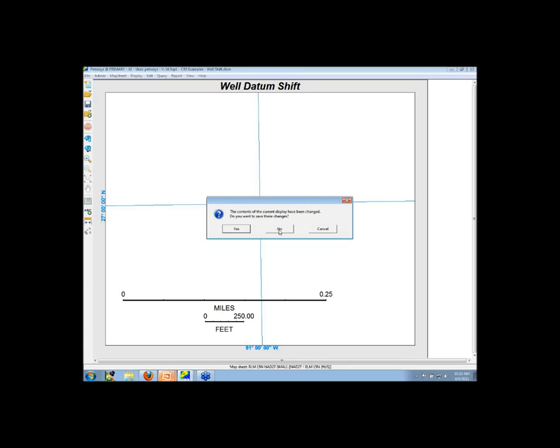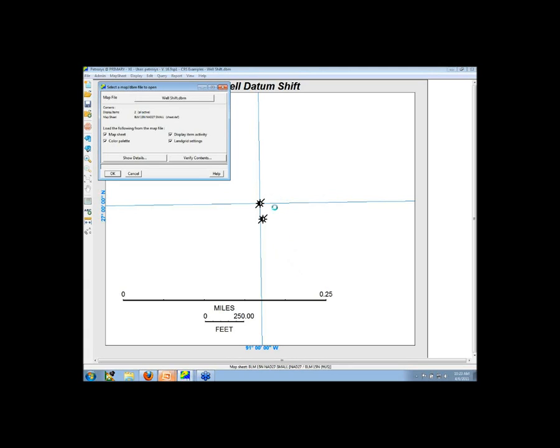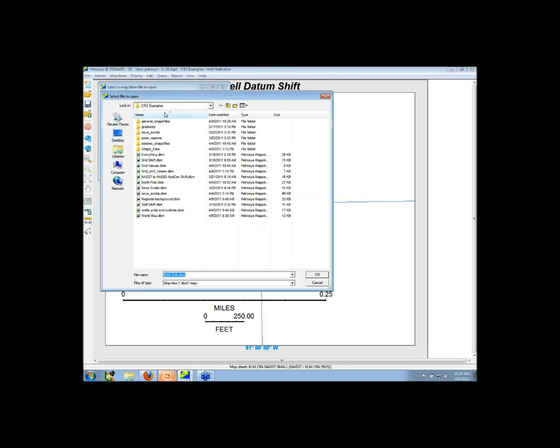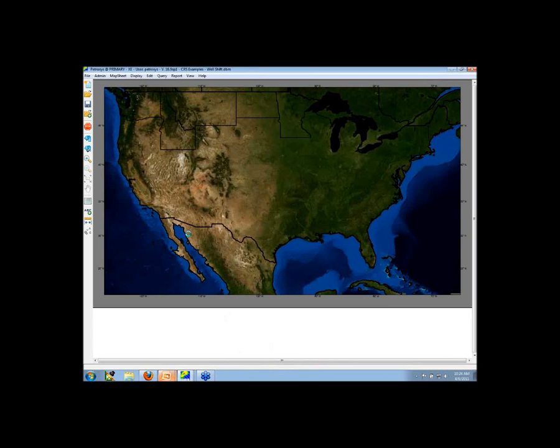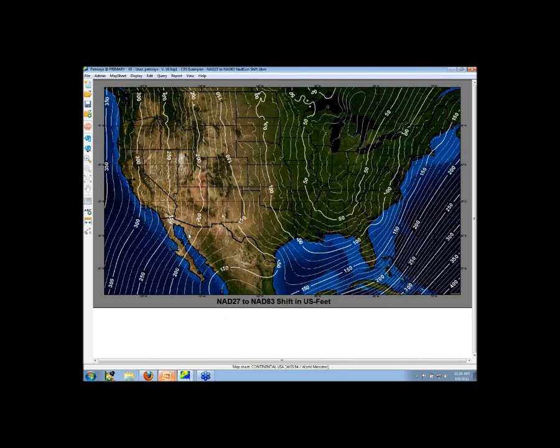And that 105 feet difference is not a constant. That's something that's going to change no matter where you are. And over the United States, like I said, we commonly use the NAD27 to NAD83. And I've got a nice little map here where we're projecting this WMS image that is being provided from spatial energy, projecting that in the background, so it takes a second. But these contour lines are showing the different datum shift amounts over the different parts of the country.